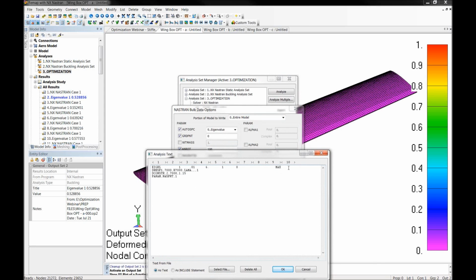to include buckling. So when you go through a buckling analysis, some of you may be familiar with the EIGRL card. This is really just defining your buckling method. So 1 is just the buckling method ID. 0.01 and 6 is the range for which I'm looking for buckling eigenvalues. 1 means I'm only interested in the first, or the lowest, buckling mode.